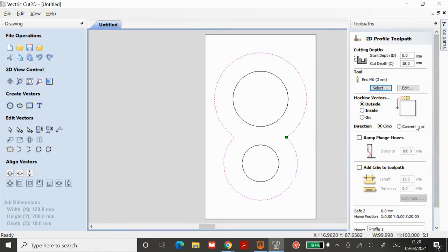Right, okay, so conventional cutting, the router would run this way round and travel anti-clockwise. The router itself rotates clockwise. So a conventional cut would be what's called upcutting, and it would be removing chips running clockwise direction and traveling in the same direction as it is cutting.